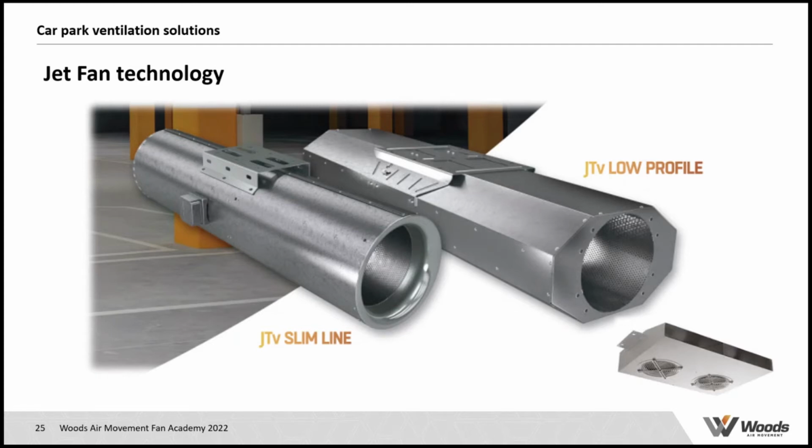The unit is a different concept. The upside is that generally the units are smaller in depth. So if you have a very shallow car park, you can quite often get away with induction fans rather than axial flow fans. But the concept and the way you design the system is actually exactly the same.